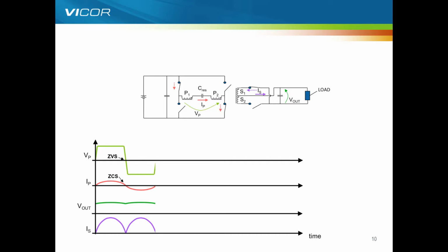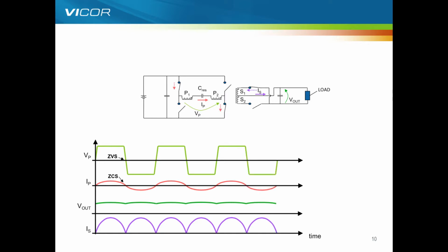When we switch those devices, so we've now got Q1 and Q4 turned on following a zero voltage transition, you can see that the primary current is a full sine wave, secondary is a rectified sine wave, and the Vout, notice, stays at that DC value, but it does have a small ripple. And as we go through, you can see the primary current is the sinusoid, and that output voltage continues with a frequency which is 2x the primary. So this is the operation of the sine amplitude converter with a fixed load.